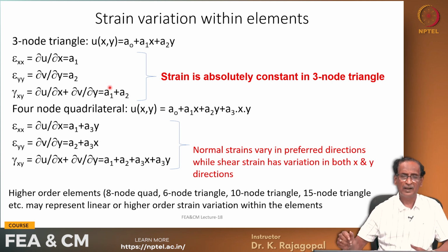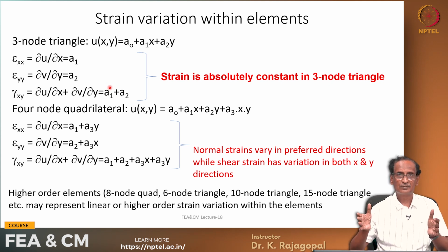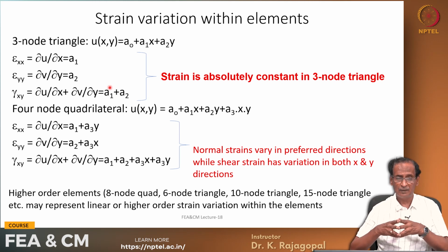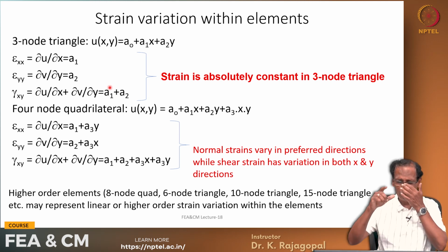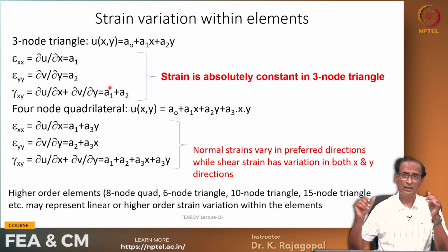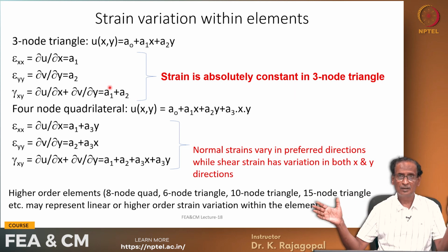So the 3-node triangle per se is a constant strain triangle, and so when you apply it, we should be careful, because if you use a very large element, then within that large area you are assuming that the strain and stress are going to remain constant.